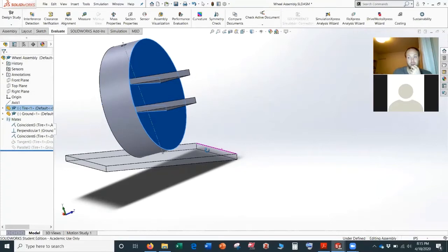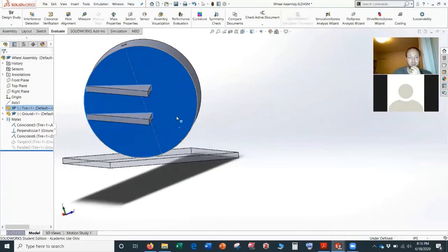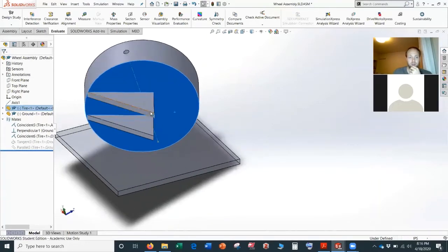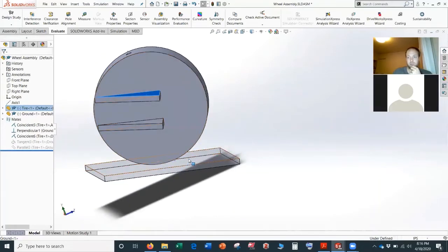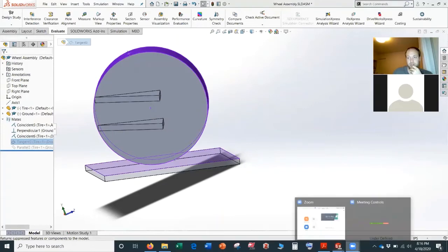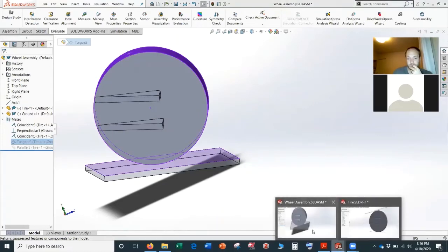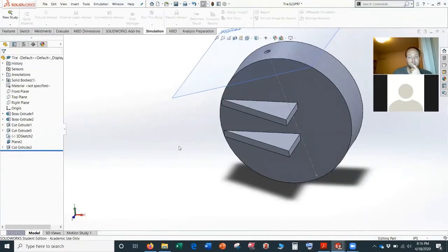It looks like they both go into the ground. So you do have the advantage of the trail, where your steering is at least stable. It's a little easier to rotate this about if you're up higher. So it's at least stable now, and your contact patch is behind the axis, right? And we talked about that with the shopping cart or caster effect. So we see it doesn't have as much of an effect without any scrub radius. So let's add some scrub radius to this thing.